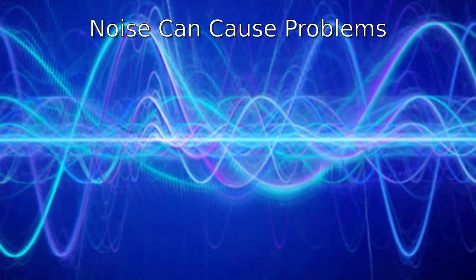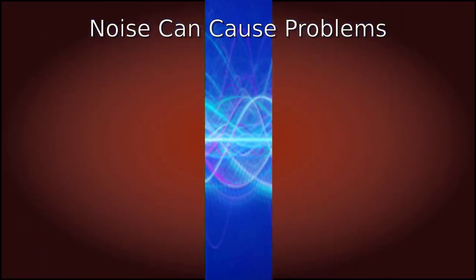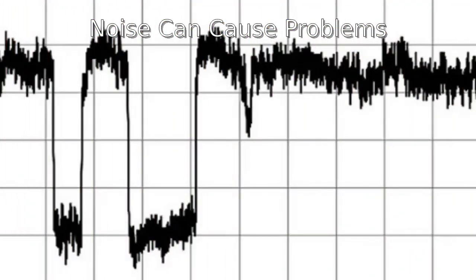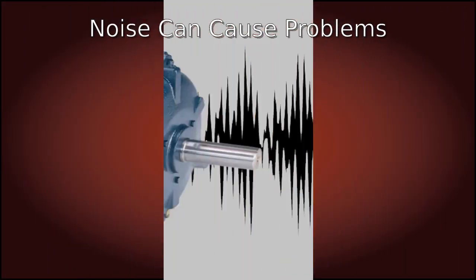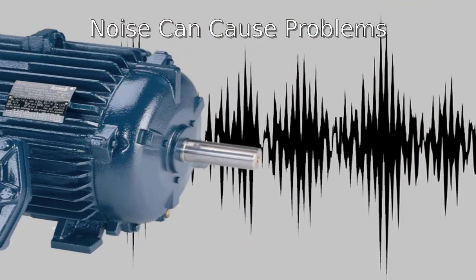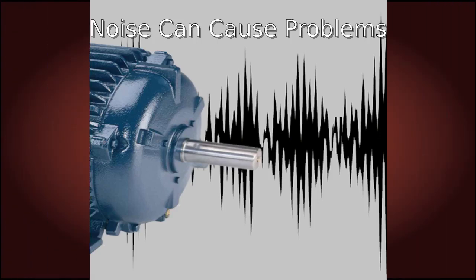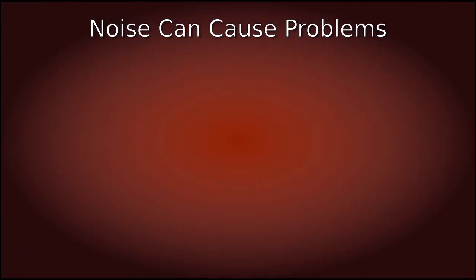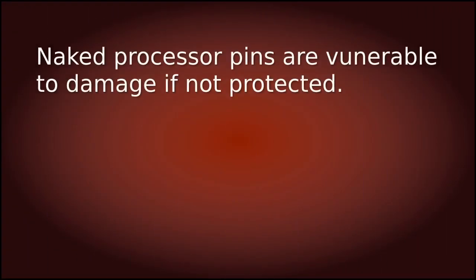Industrial environments usually contain noise in the form of voltage spikes, RFI, EMI, ESD, lighting, motors, welding equipment, relays, contactors, and power systems, to name a few. These can cause potential problems for sensitive microprocessor applications if precautions aren't taken. As for the Arduino Nano V3 PCB, its processor pins come directly out on the male headers. This allows flexibility with pin functions, but exposes the processor directly to potential damage from noise.